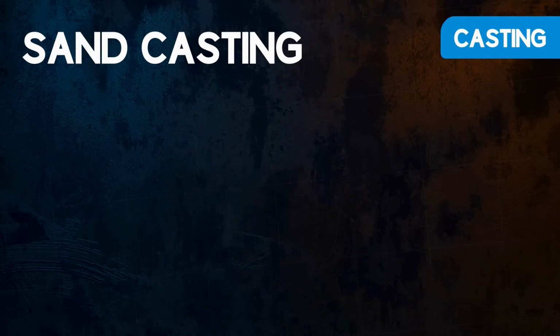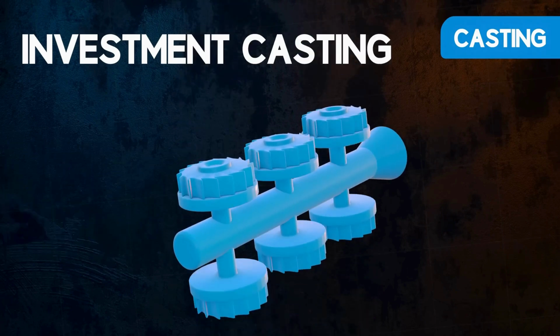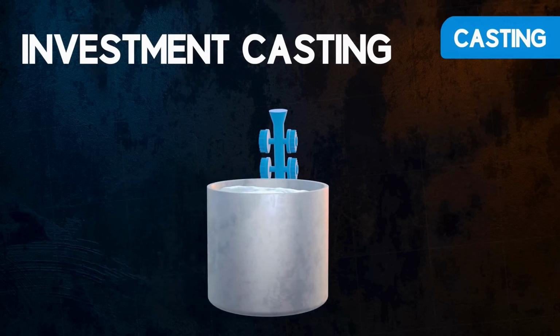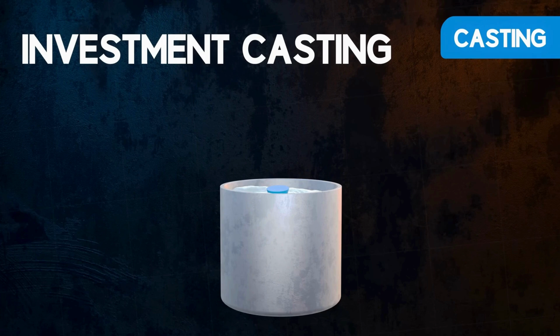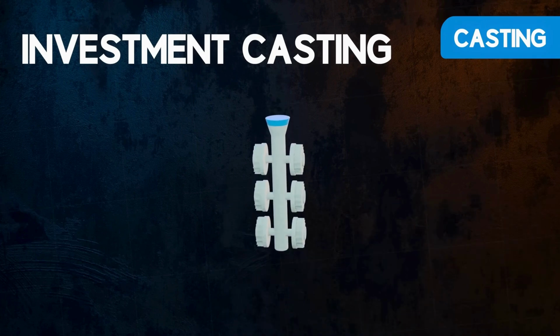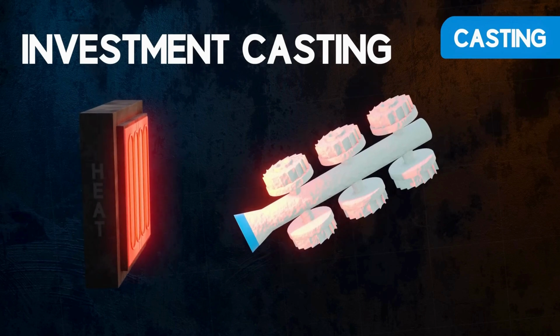The last casting process we will look at is investment casting. Several wax patterns of the same object are created and attached to a sprue. The wax tree is dipped into a slurry to create a ceramic mold. Heat is applied to melt out the wax.